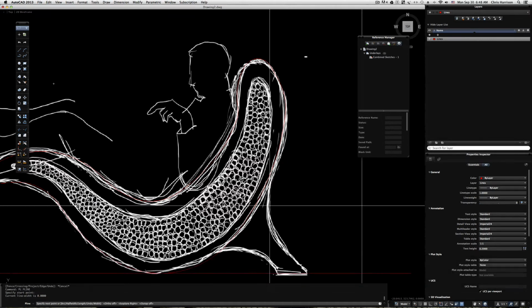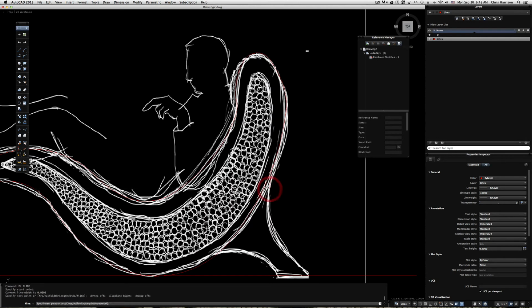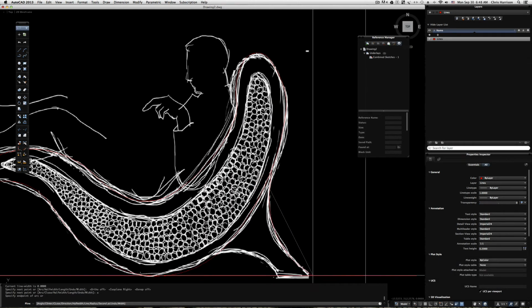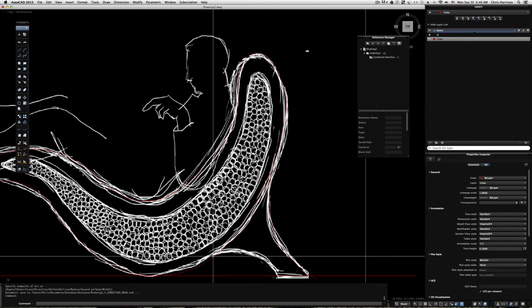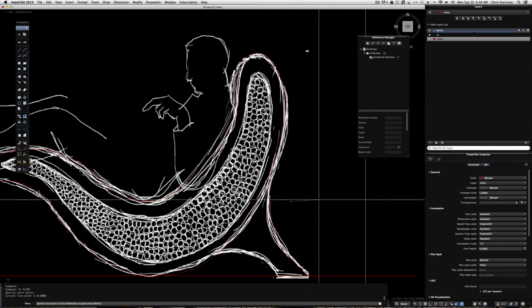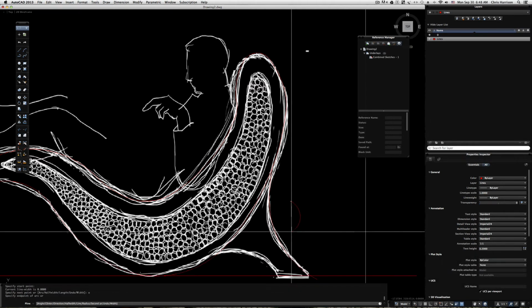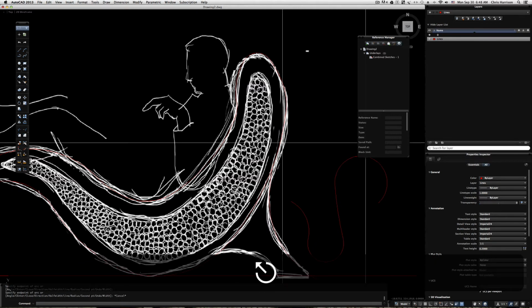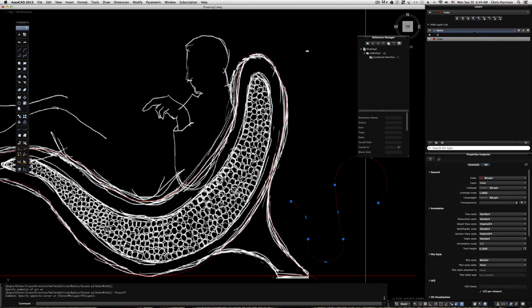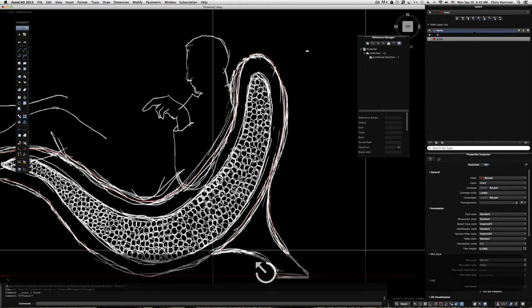Okay, so following that line, A for arc coming down. Polyline again. Now you'll notice that if you hit a point and you want to immediately do an arc, so you hit A for arc, you can do that. That's fine. Typically, when you draw these shapes, though, you want to give yourself at least one straight line segment. And let me demonstrate that. Actually, this might work because it looks like it's a perfect arc, but let me demonstrate.